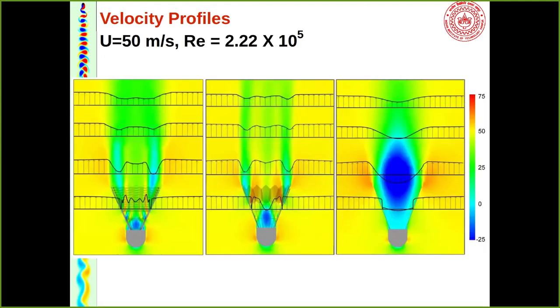Okay, this is the flow. So this is your synthetic shuttlecock. This is the duck feather, and this is the gapless, the skirt. You can see the thing which determines the drag is the momentum deficit. So even though this has a very large recirculation zone, the momentum deficit is much smaller. You can see it is very large here, small here, and very small here. So how much momentum am I using in a given control volume?